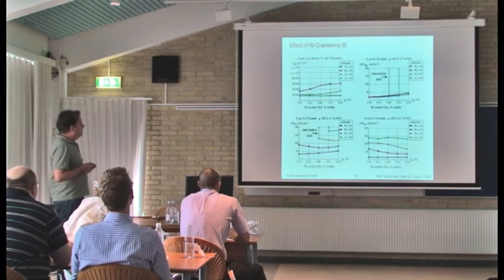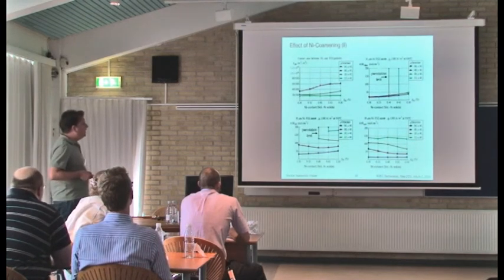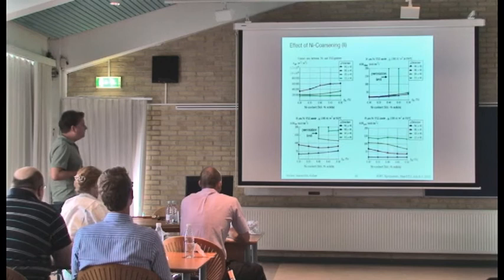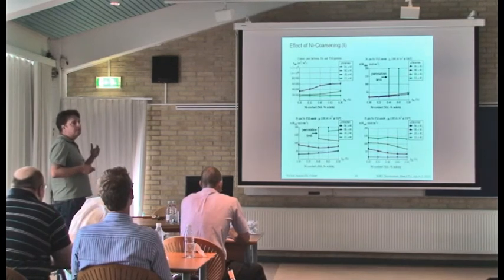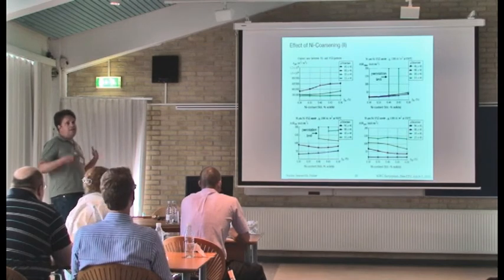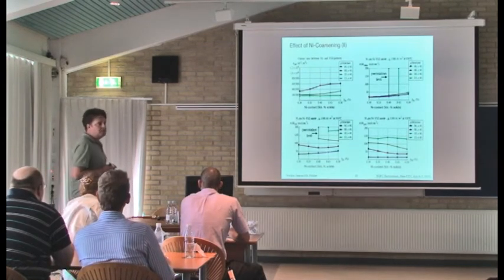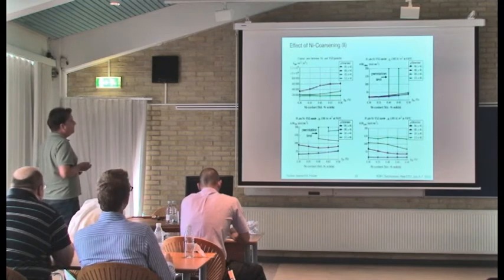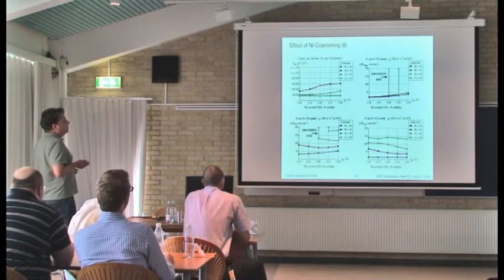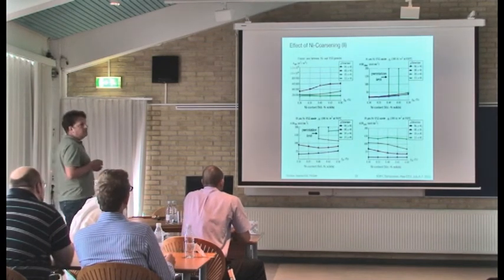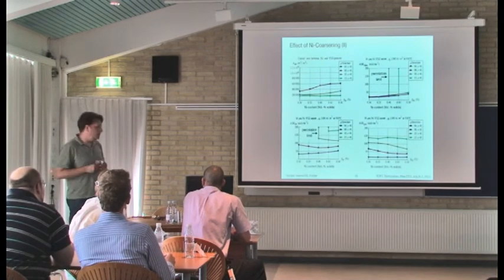So you see here the polarization resistance, which also changes. The overall level increases when you get coarser particles. Makes sense, because then the triple phase boundary decreases. But what really kills your electrode is this sharp increase in the ohmic resistance at the percolation limit.